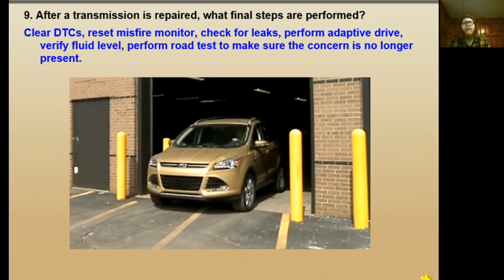So you can see how these layers create a lot of nuance, and so we drive the vehicle in a specific way, which is outlined by the workshop manual, and that specific type of driving gives the computer time to make these measurements and to adapt to them. Also, the type of driving helps the transmission control module, PCM/TCM, know that it's being driven in an adaptive cycle, and it will record the information and store it in a more meaningful kind of way.